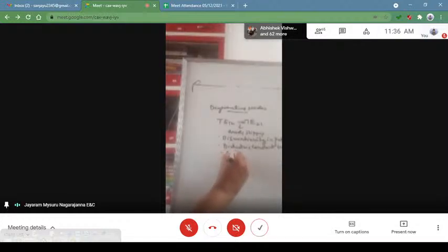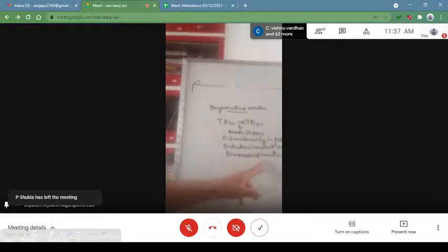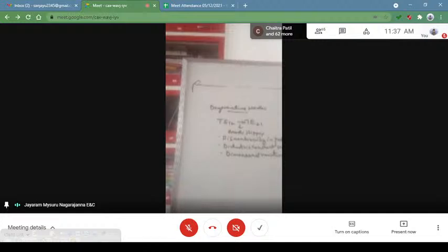Another thing is dimensional variation, because we have stated the width should be A and the breadth should be B. There may be micro variations in the dimensions because of fabrication problems. If the waveguides are not properly fabricated, there may be small variations in the width as well as the length. That causes a micro variation in dimensions, so that also causes mode slipping.